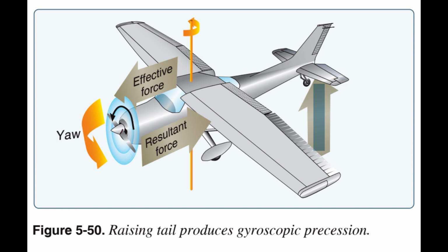Depending on where the force is applied, the airplane is caused to yaw left or right, to pitch up or down, or a combination of pitching and yawing. It can be said that, as a result of gyroscopic action, any yawing around the vertical axis results in a pitching moment, and any pitching around the lateral axis results in a yawing moment. To correct for the effect of gyroscopic action, it is necessary for the pilot to properly use elevator and rudder to prevent undesired pitching and yawing.